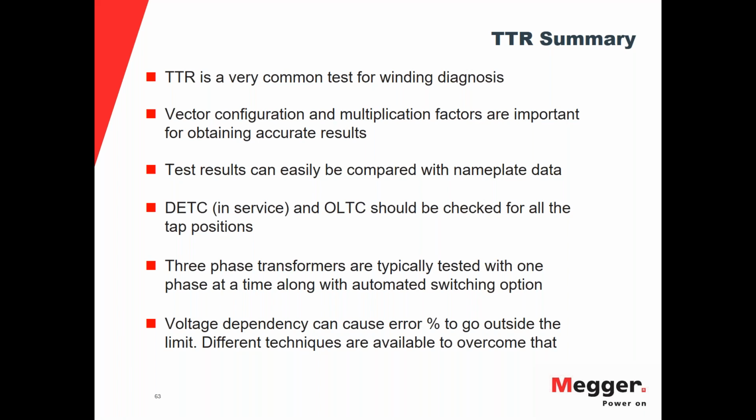Three-phase transformers are typically tested one phase at a time, along with the automated switching option. We also looked at doing three-phase transformers with a three-phase simultaneous test. And then, of course, we talked about the characteristics of voltage dependency as well as some different techniques to overcome that.